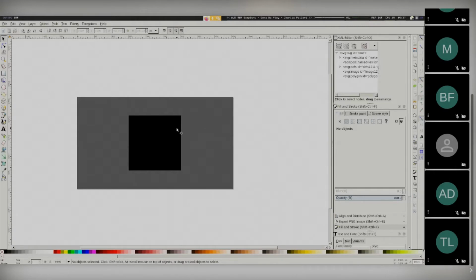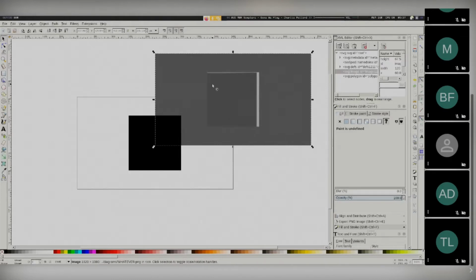cutting from an IFC is a slow process. The geometry in IFC is not, let's say, optimized for cutting, and so it may take a very long time. And often there are many objects in the background you just don't need to cut. So for now, the default option is to just render out a raster background.